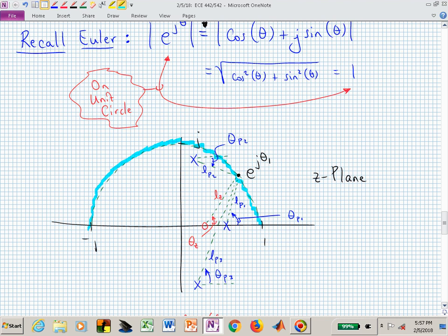Yes? For the number of poles in this loop, is it only the finite ones, or is it all of them? So now the question was, the poles that I'm referring to in the system order, does that only involve the finite poles, or does that include the poles at infinity? It's only the finite poles. So it's only the poles that are visible on the finite plane in Z. And we probably won't have infinite poles, because that would mean that our numerator polynomial was of higher order than our denominator polynomial. We'll stay away from that.